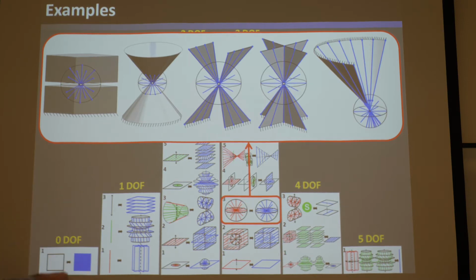That top body with respect to the ground would move like a sphere centered around that point, a red sphere centered at that point. Okay. Same thing with this one right next to it. This is basically the same, two opposing V flexures, but they're fused down this central axis, and so they count as one element, and they move the same way.